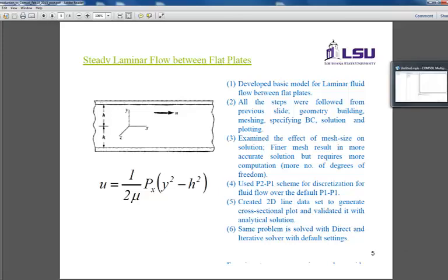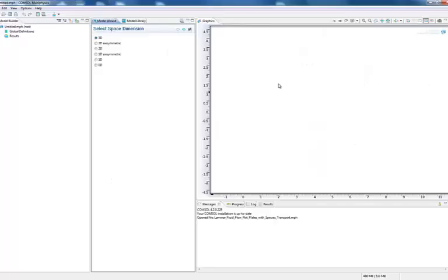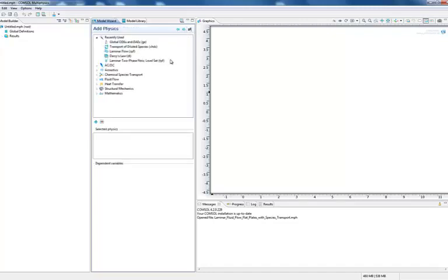If you open COMSOL, this is the first screen you're going to see. Because our model is 2D, let me select 2D as the space dimension and click on the next arrow. After that, these are the recently used modules, so I'm just going to minimize this, and now you can see there are different physics nodes shown here.